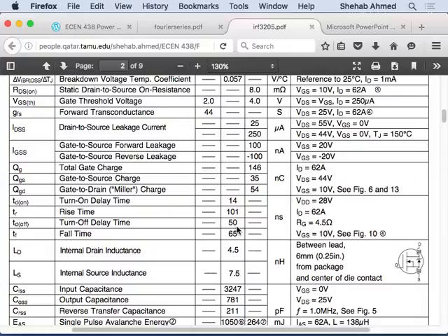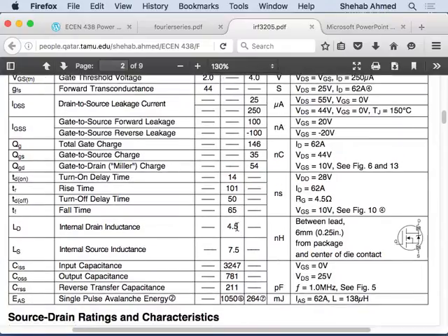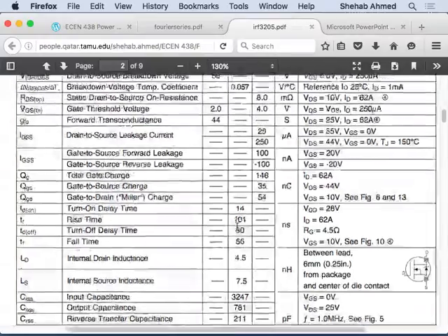Right? That's the whole objective of what we're trying to do here. Okay, so they're all tied together. If you increase switching frequency, I can use smaller capacitors and inductors. But if I use increased switching frequency, I have to choose the proper devices, and I have losses. It's a compromise between the losses in the devices and the losses and size of the capacitor, etc., etc. Right?